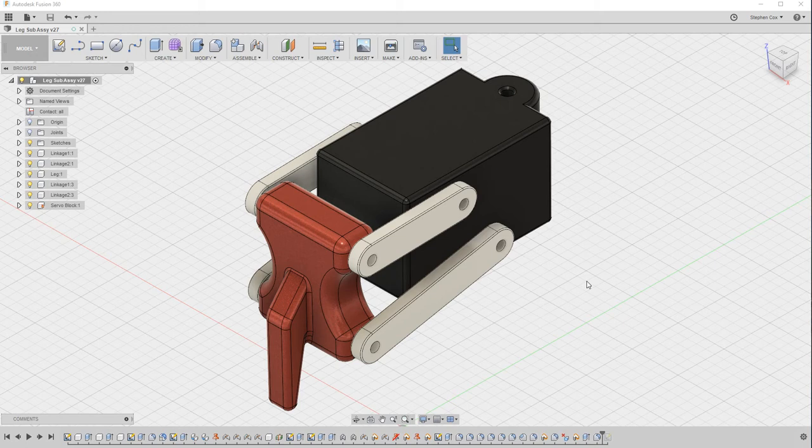So we're now going to look at how you can create 2D drawings from your Fusion 360 designs, and the way you do that is switch out of the model environment into the drawing workspace. And we've got two different options for the drawing workspace: drawing from design, which is the one we're going to choose, or drawing from animation, which may be if you've created an exploded view in the animation workspace, then you can create a 2D drawing of that exploded view.